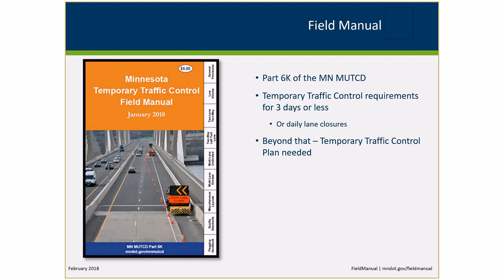Now, this document is meant to be used for temporary traffic control of 3 days or less. It could also be used for more long-term projects if you've got daily lane closures. If you go beyond that time frame, though, there really ought to be a temporary traffic control plan developed by the road agency or by a consultant working for the road agency, and then that gets published as part of the plan, and that's what gets followed. But for 3 days or less, this is the document that you would end up using.